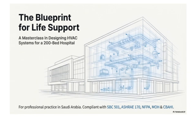We'll explore how the design must adhere to standards like SBC 501, ASHRAE 170, NFPA, MOH, and CBAHI, and how every HVAC decision is treated as a clinical safety decision. Ultimately, we'll see how hospitals are engineered as pressure-controlled, filtered, and zoned environments to support optimal healthcare outcomes.